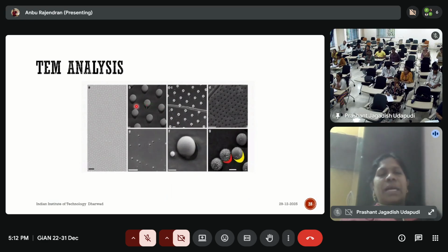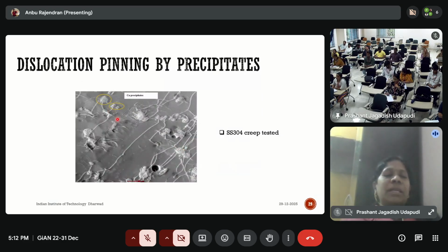Okay, so these are small particles embedded in a matrix. These particles can be revealed by TEM. This is one of the samples, the one whose macro image and SEM I showed, with precipitates. Those precipitates are larger. In some conditions during creep, the same sample formed very fine grains. You can see 20 nanometers is the scale size. So such small precipitates, and this is the dislocation.